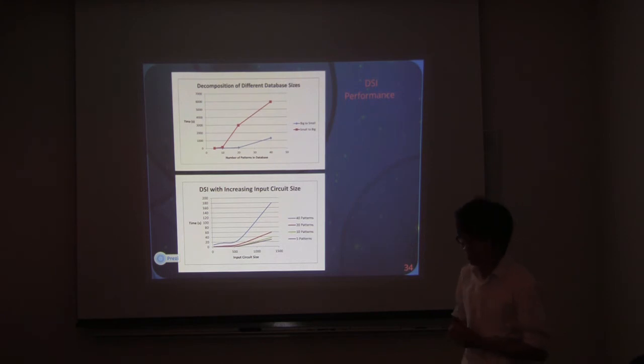Is that important, or are you ever requiring that you flatten your whole design and apply these algorithms? As for now, I'm assuming that a lot of the circuits used are fairly flattened to primitives. Can you apply these algorithms to circuits that aren't flattened? I think it should be able to. There's no problem doing that, except the patterns would have to somehow correlate with or use the hierarchical blocks. So if your design used an adder, and you want to match a counter that uses an adder, then instead of the patterns being flattened, you would have to have the patterns in a hierarchical form as well.